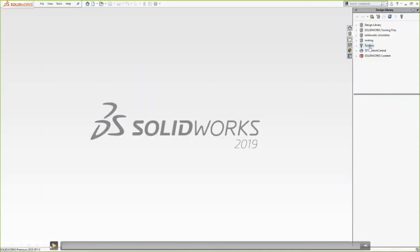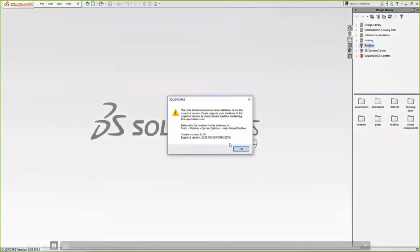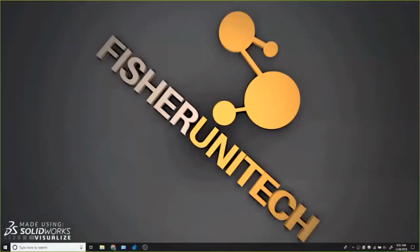So to start off with, let's just take a look at what's going on. I'm loading my SOLIDWORKS toolbox, and I get this error that says, hey, you're working in 2019 here. Your expected toolbox version is 19, but you have a 2018 toolbox. So I say, oh no, I need to fix that. So I'm going to go ahead and close SOLIDWORKS, and I'm going to open up